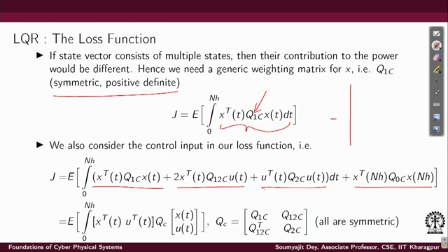Suppose I am trying to choose the control input right now, but I am not only worried about the effect of this control input at this kth time instant, or in the interval k to k plus 1, but the effect in the long run, up to some finite horizon of size n. That means I want to capture mathematically how to choose this u so that the cost function is optimized not only in this period, but over a finite horizon, let us say over the next n successive periods. I want to know about that. So, that is why n comes as a parameter in this design.